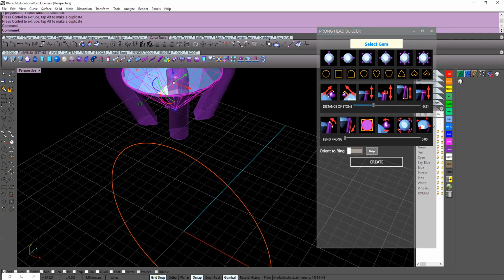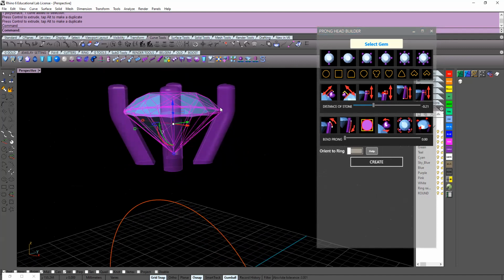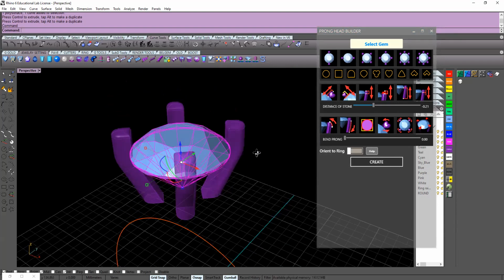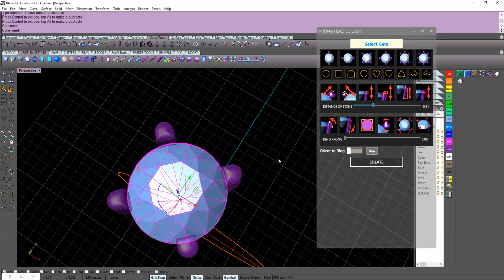When you end up cutting your seats for your stones, you don't want to go more than 1/3 of the way through your prong. So I don't need to design for it halfway through my prong. Then my setting would be too small.